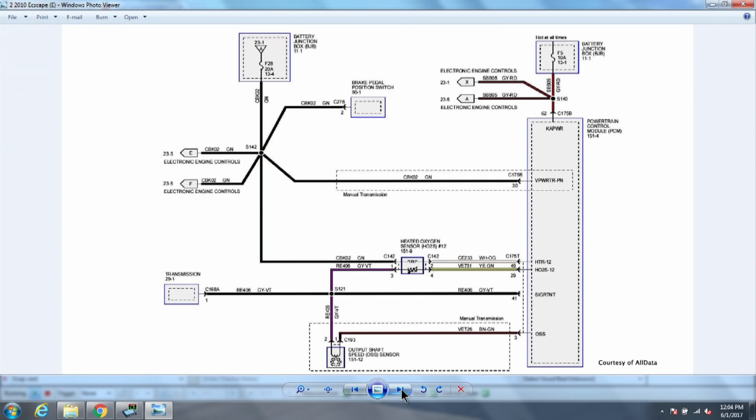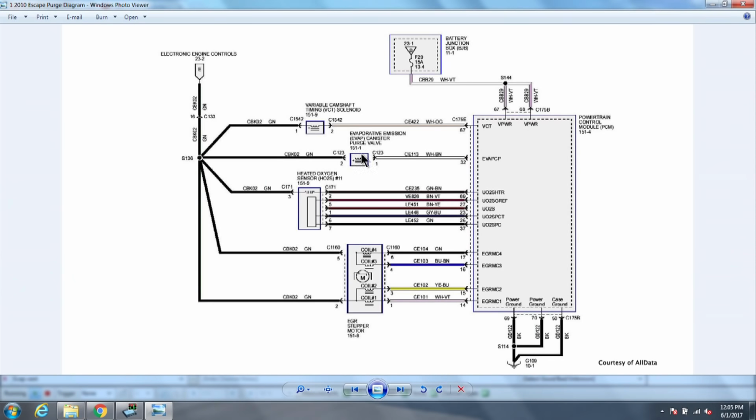Let's look where pin E goes. Pin E goes here to a splice to a fuse that comes from A. So a 20 amp fuse is going to power our pin E, which is going to be our input into our purge solenoid. Now I wish I had one of those cool touch screens so I could draw on the screen for you guys, like in New Level Auto's videos. He's been doing that. That's pretty awesome. Okay, so we're there.